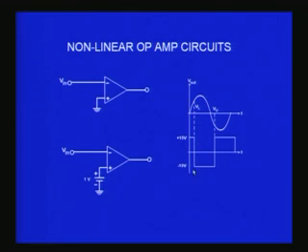There it becomes minus VCC, minus 15 volts, and when the sine wave comes to 0 next time and goes below 0 by again some 140 microvolt or so, then because this input will become less compared to this, the output will become plus VCC, and therefore the output will again shift to plus VCC as you see on the graph. So the bottom graph, the square wave that you see, corresponds to the output, and the sine wave above corresponds to the input for any of these circuits.